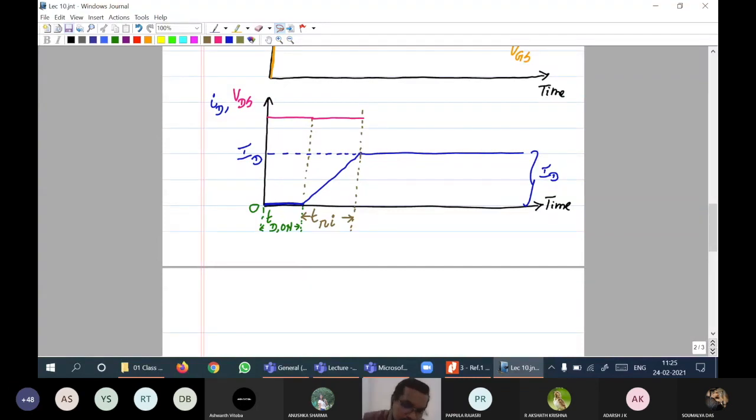That's all. So those two regions correspond to the fall in voltage of the MOSFET, which is the drain source voltage. Again, remember, from cutoff to active region, the fall will be steeper. We had come across these things in power BJT also. It will be steeper. From active to ohmic region, it will be flatter. So you have to draw it that way. Let's say, steady state value of VDS must be reached. So it just falls drastically.